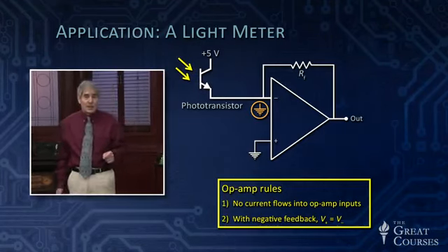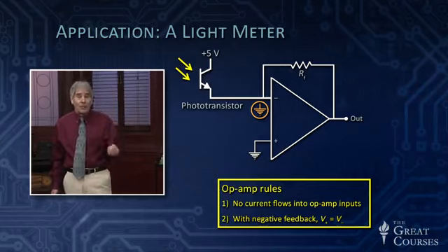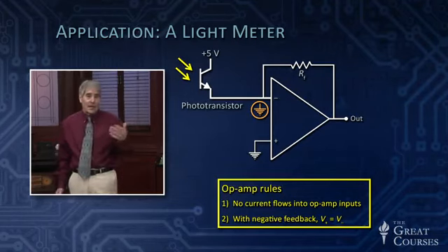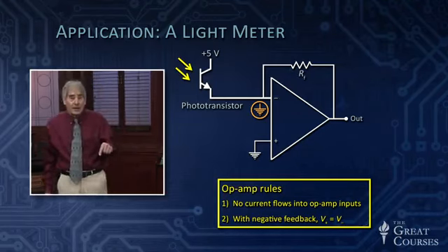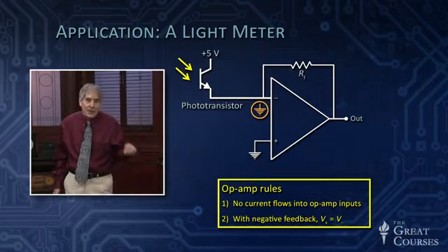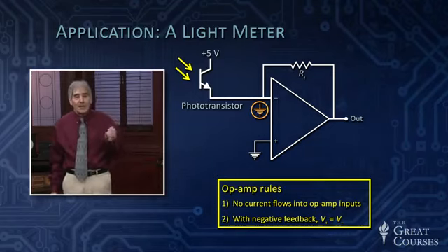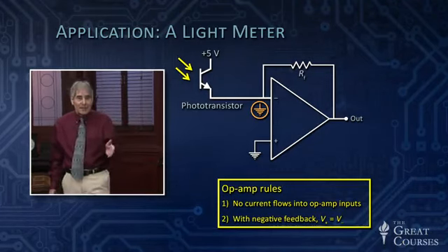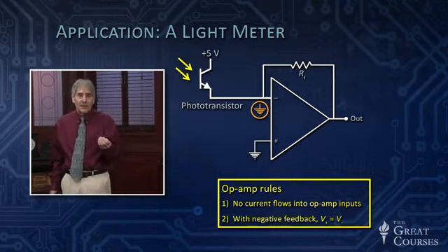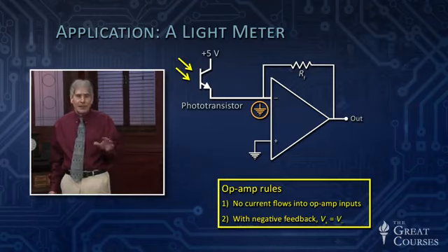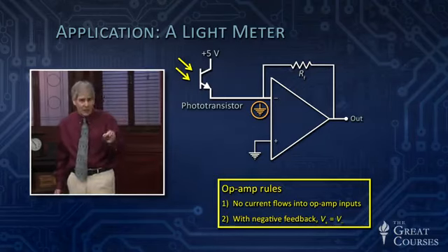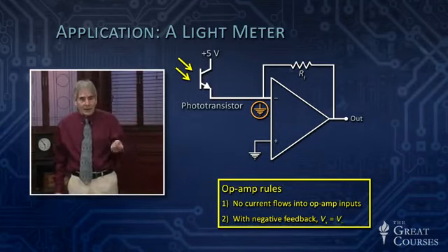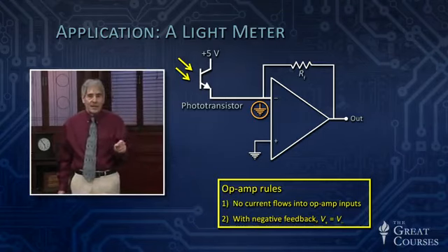What a phototransistor does is it uses light to produce electron-hole pairs at the base. And when you connect a voltage to its collector, this is an NPN phototransistor, similar to the NPN transistors we've been using, you will get a current that depends not on a base current, because there's no connector to the base, but depends rather on the intensity of the light falling on that base. These transistors are built in transparent plastic cases. That base is exposed to light, and when light falls on it, the energy of the light creates electron hole pairs. It's very similar in some ways to the operation of a photovoltaic cell, although a PV cell is just a diode, and this is a little more complicated because it's a transistor. Well, that transistor produces a current that's dependent on the intensity of the incoming light.